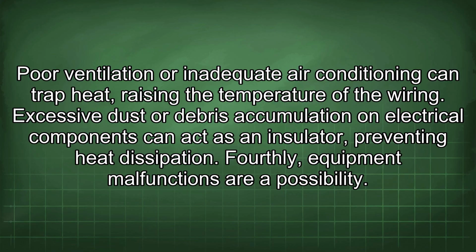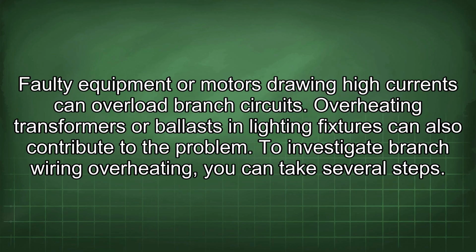Fourthly, equipment malfunctions are a possibility. Faulty equipment or motors drawing high currents can overload branch circuits. Overheating transformers or ballasts in lighting fixtures can also contribute to the problem.